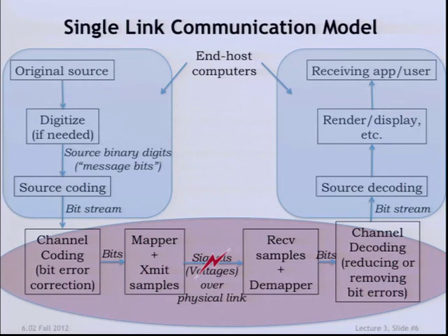Now, here's the funny thing: we've just done a lot of work to extract redundancy from the messages, and we're going to put redundancy back in, because the way you guard against disturbances in the channel is by introducing redundancy. You need to give yourself a little room to recognize that something bad has happened to your signal or to the data you're sending across, and then to recover from it. So we will be talking about how to reintroduce redundancy, but this is introducing it now in a bit stream where the binary digits are essentially equally likely.